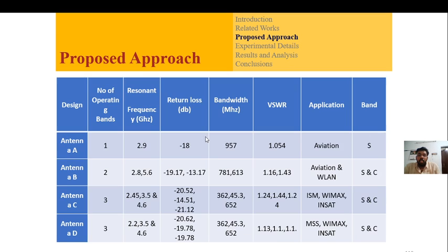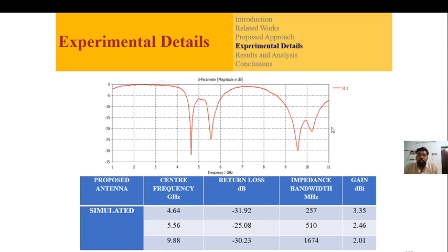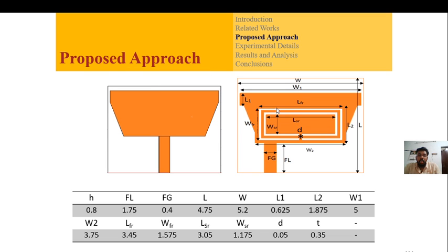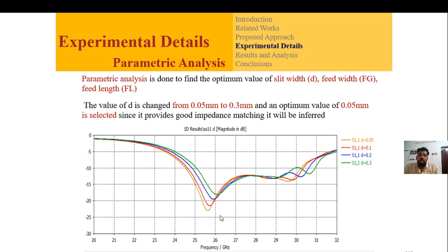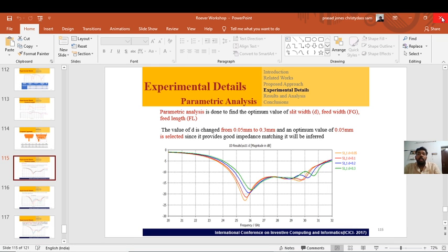So here after introduction of a split ring resonator, I can achieve multiple bands, and this is for the radar. Co-directional CSRR has been used, and here you can view it can be operated from 25 gigahertz to nearly 31 gigahertz. So this is for short range radar. So these are some of the research details, right?